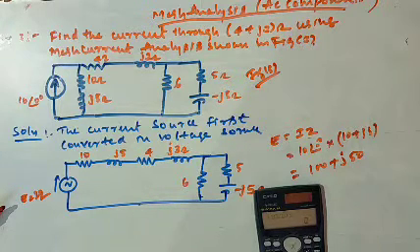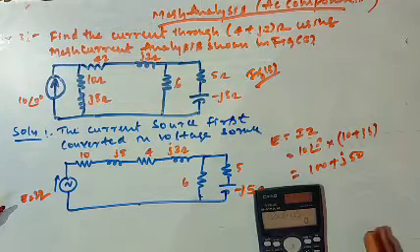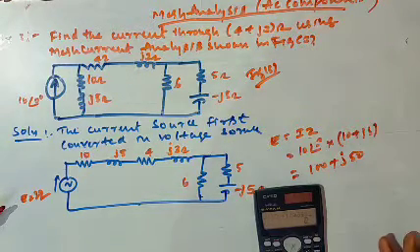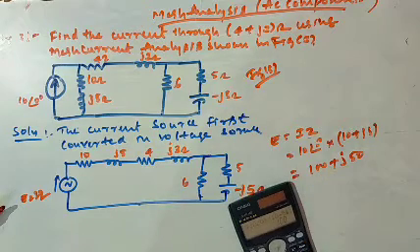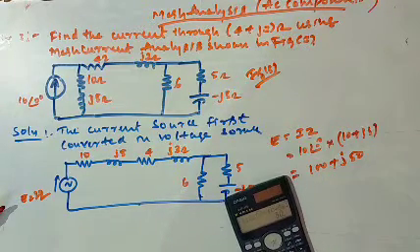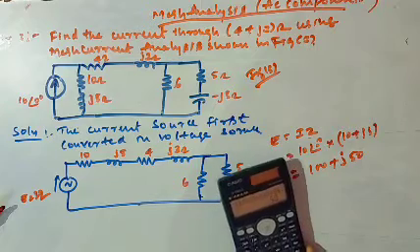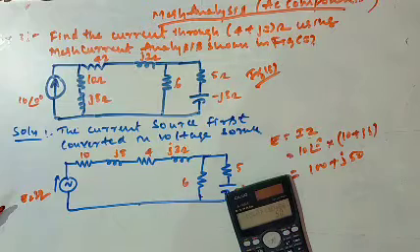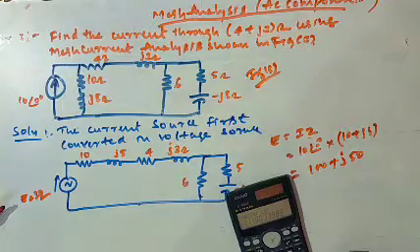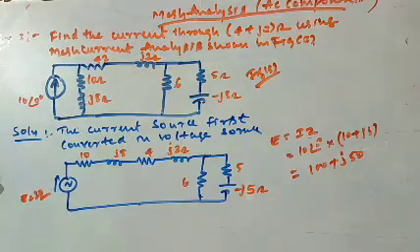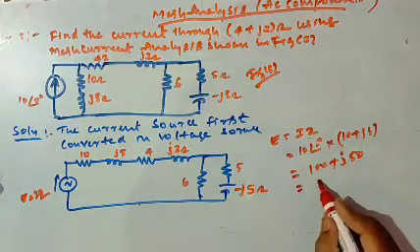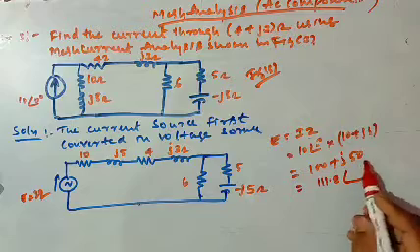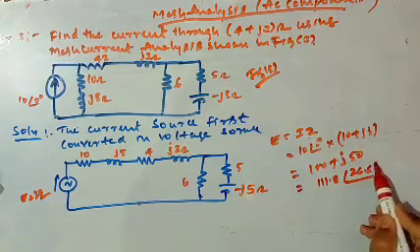Multiplied by, if the bracket is there, no need to give the multiply sign, 10 plus 5 I. If you press that, you will get 100, and pressing shift equals, you will get 50, the imaginary component, that is 100 plus J50. Press shift and convert to angle, that is 111.8, and the angle is 26.565. So this is 111.8 at an angle of 26.6 degree.